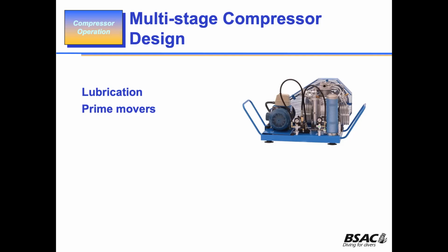Which then does away with all the aggravation of exhaust and engine leaks. If you've got an electric motor, you can more or less have the whole lot running without any worry of contamination to the air that you're sucking in. If you've got a petrol or internal combustion motor driving it, you've got to make sure the exhaust is well away from the inlet, somewhere in the region of 2 or 3 meters, socially distanced, of course.